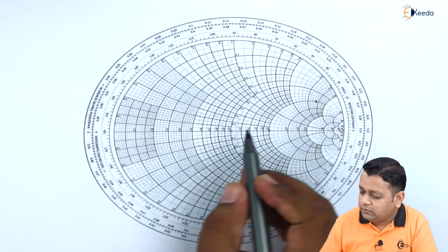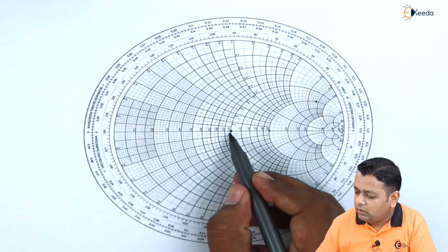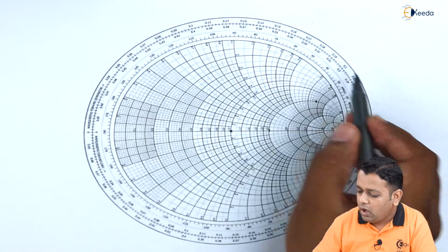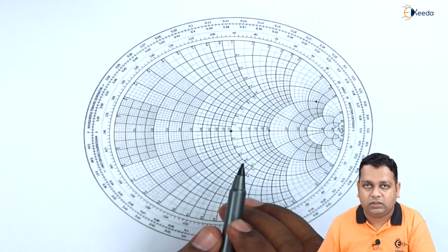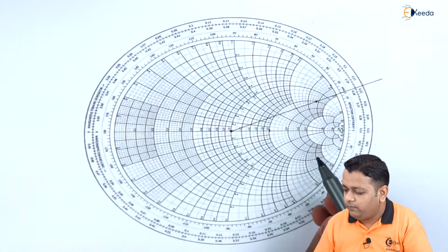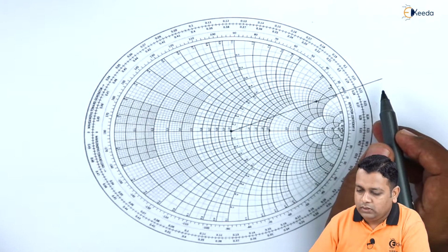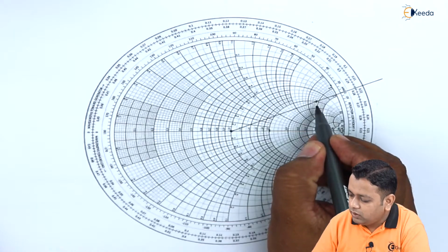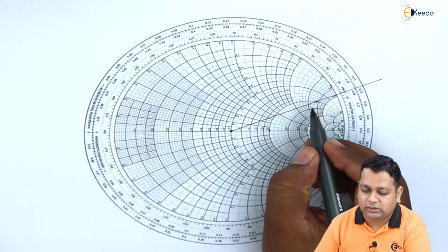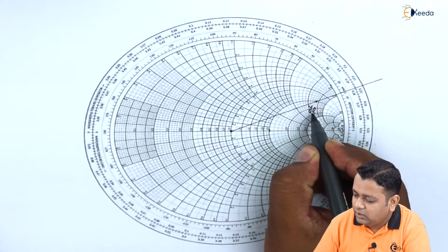The center of the Smith chart is here. Now we can connect the 2 points so that it intersects the scale on the outer region of the Smith chart here. When we join the 2 points, we see this is the marking on the scale here. So now at this particular point where we have added the normalized admittance, we can mention this is nothing but Y suffix L here.